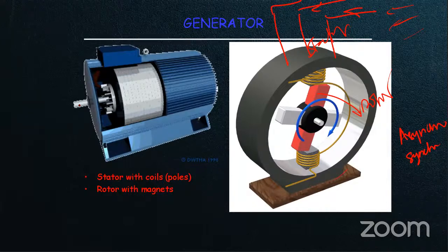Here the generator is coupled with the shaft, meaning the gearbox shaft, and the gearbox shaft is connected with the rotor. When the rotor speed is higher, I mean when the wind is stronger, it generates power from the wind, and to push the power to the grid, the flow goes in the opposite direction. Initially it draws power from the grid; once we have more power from the wind, the rotor pushes the power to the grid through wire to the stators.